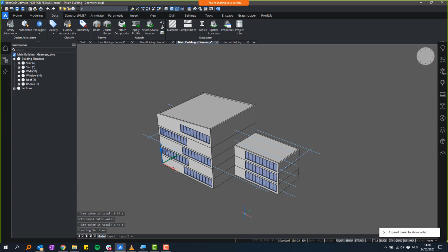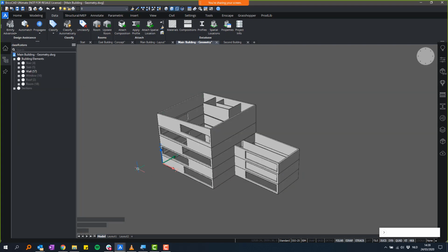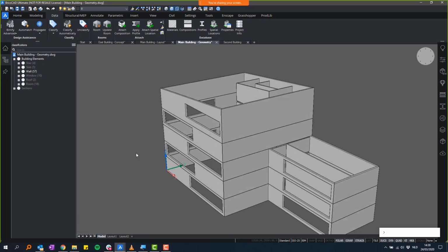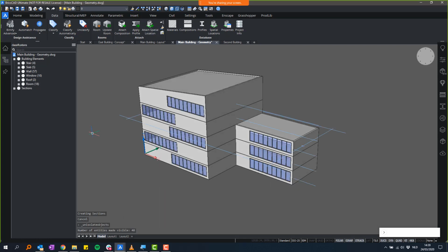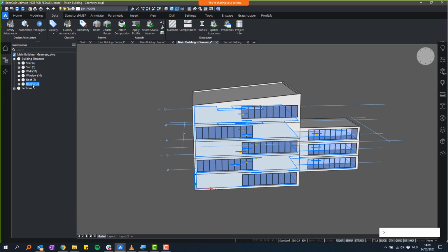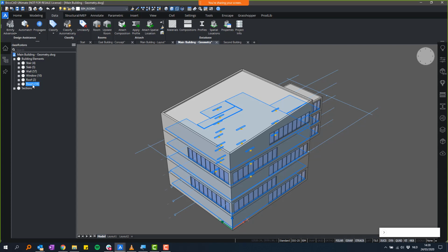we will see in just a second that now, instead of just having solids and block references, we have 4 staircases, 5 slabs, 57 walls. If I isolate these walls, you can see it's done correctly, so it recognized everything correctly. Some windows, 2 roofs, and 18 rooms. So these rooms were also detected automatically by Bimify. It detected the spaces inside solids and made rooms inside them.